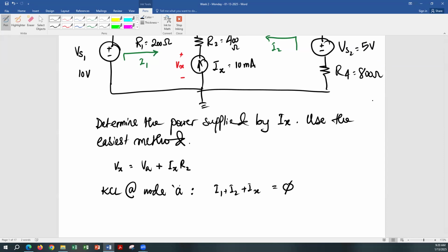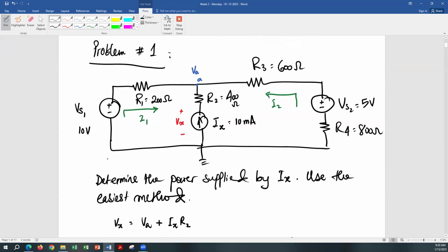So now you're going to put what you were telling me earlier, the nodal analysis, right? Before you apply nodal analysis, make sure you write the KCL equation first to show which currents are going away and which are going towards, and then you apply Ohm's law and write the nodal analysis equation. So now you apply Ohm's law. What is I1? Vs1. Yes, go ahead.